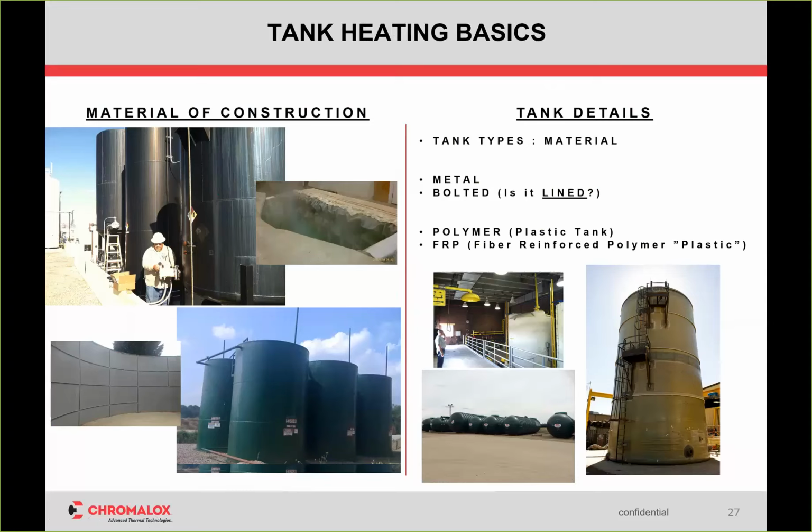The problem with fiberglass tanks and polymer tanks is they'll be rated physically for ANSI sizing or Schedule 40 piping or metal spec. They're physically the same size or bolt pattern, but they're always a little bit out of spec. So the nozzle itself is a little tighter. The bolt pattern's right, but the flange itself is a little off, thicker. So there's a lot of considerations. Just know if it's a polymer or an FRP tank, we absolutely can heat it. However, we need to talk about it a little bit more in detail so we get you the right product.